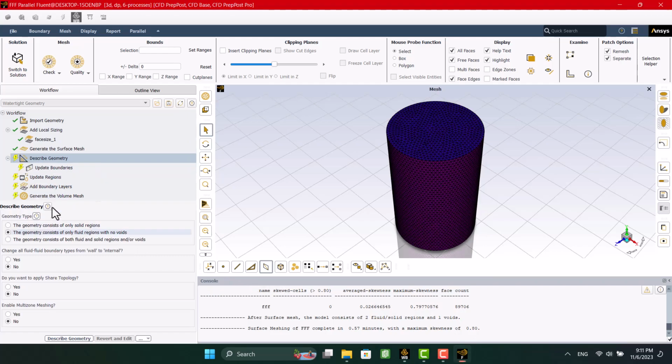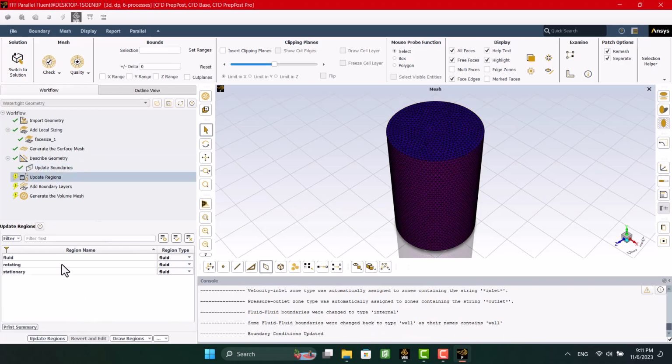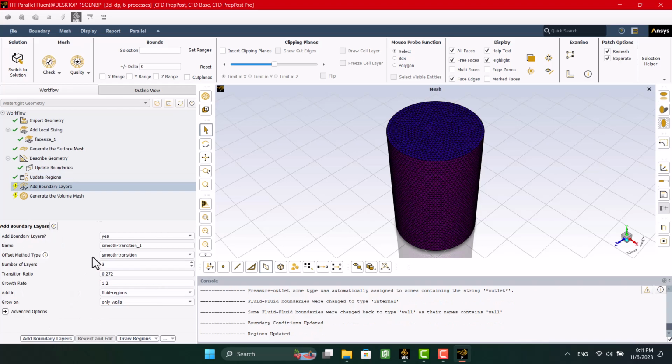There is no solid in the geometry. There is no wall between the rotary and stationary domains. I want to calculate propeller noise in stationary, so I'm going to define a pressure outlet for the inlet boundary. The fluid region name indicates the propeller volume, which I deleted. I have to change it to dead, because it's not a fluid structure interaction problem.